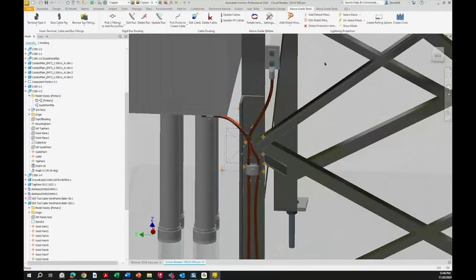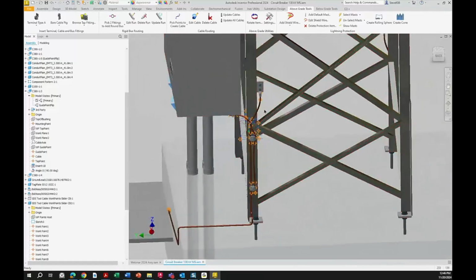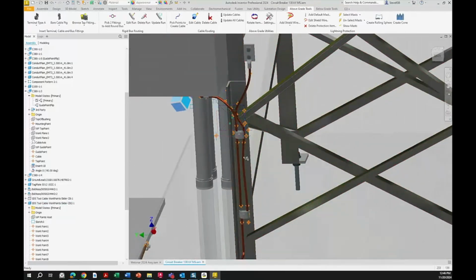And I can put that same edit in here and stretch things around. What happens sometimes, depending on the length of cable and that, is how many points you have to bend around. This one is something you can repeat on, update, and always be there. If I wanted to change this cable and I had those work points moved in, or the sketch points moved in a 3D sketch, I'd have to move those sketch points again. Whereas in this one, I'd have these points that I could work with the update.